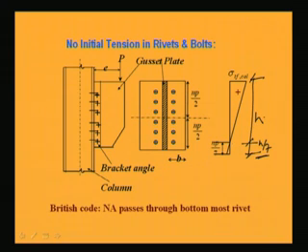So, if we consider the neutral axis here, then accordingly we can find out what stresses will develop in different places. Above the neutral axis generally tensile stress will develop, and below the neutral axis the compressive stress will develop. So, we have to make the total compressive force equal to the total tensile force.